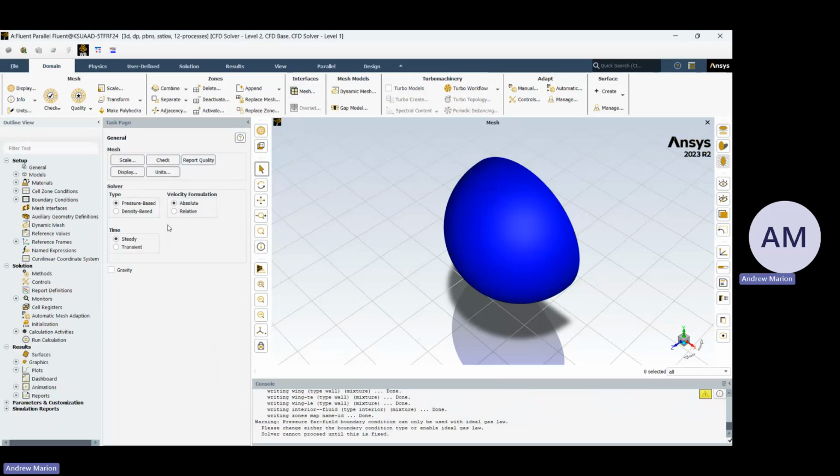Alright. So is everyone else on the screen? Not yet. He had a fatal flaw in Fluent. It came up and said fatal error and crashed. Just try opening Fluent again. But if you're doing this, close out Workbench or else they'll interact with each other.